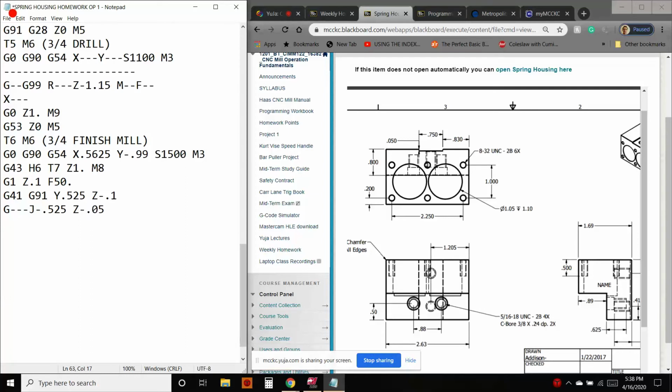Now here's a trick I'm going to teach you, this isn't going to be on any test or anything, but you can give this line of code an L value, and it will loop it as many times as the L that you give it. So since we're at Z0 now, even though we told it to incrementally move down to Z minus 0.1 because we were at Z 0.1, which is absolutely now Z0, we need to go 1.050 deep.